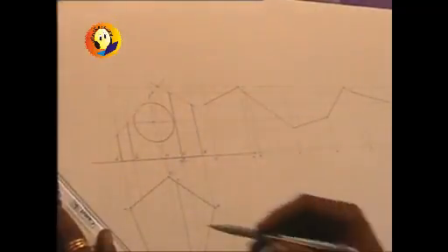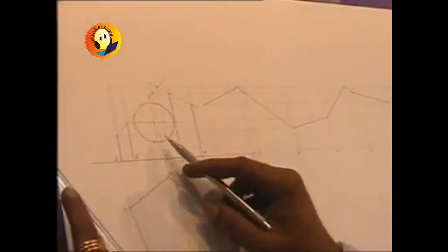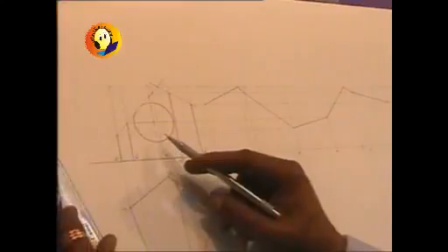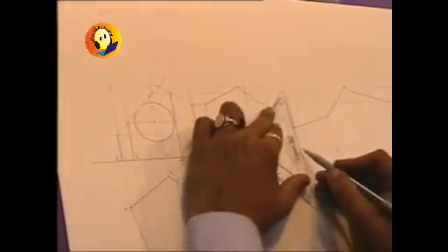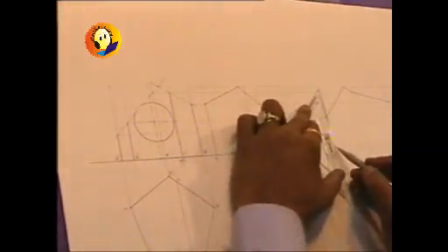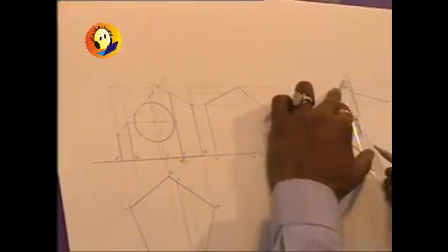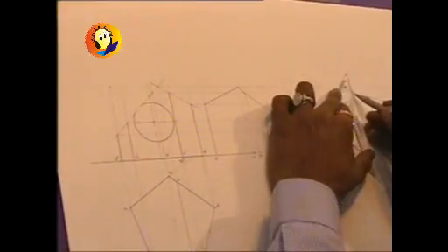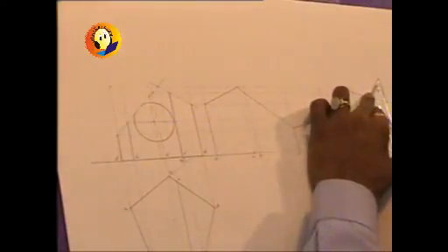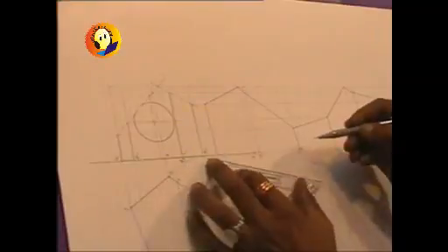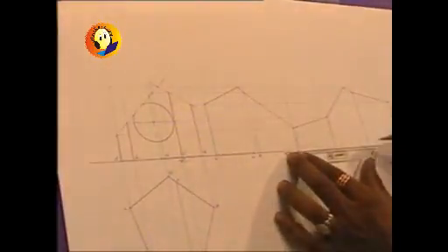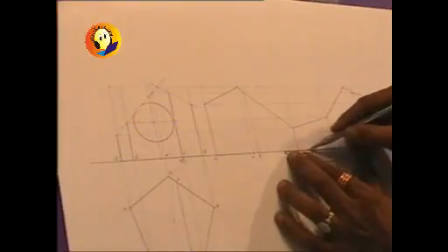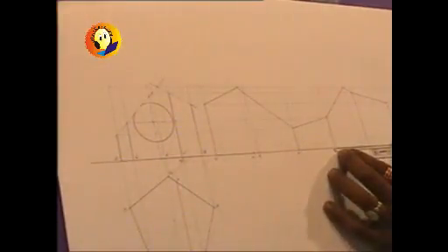We can darken the generators which are not cut by the circle. Circle is cutting only generator E. So except that, other generators can be made dark. So this is how the development will appear if only the section planes were given to us. We can treat it as a sub problem, because only this itself will be a problem of development when the prism is cut by 2 cutting planes whose positions are specified.